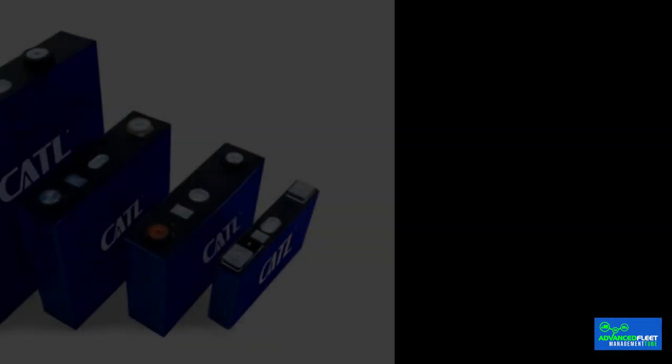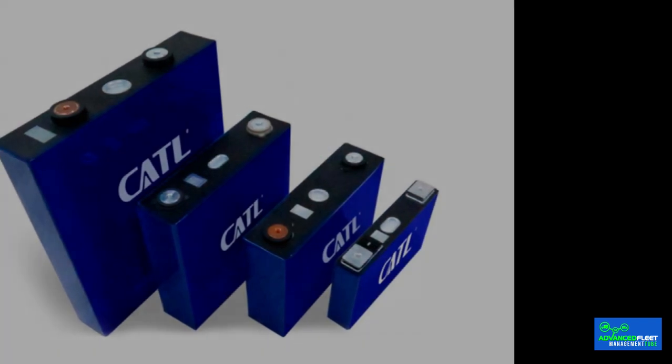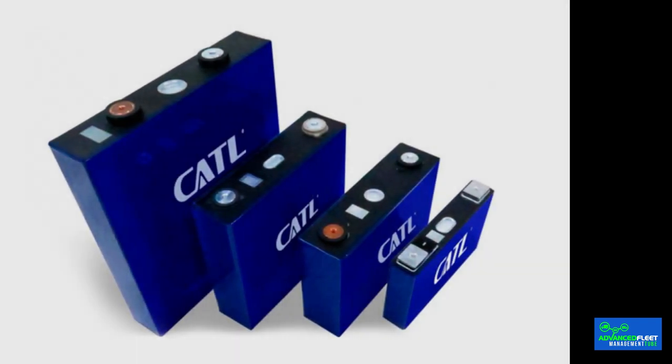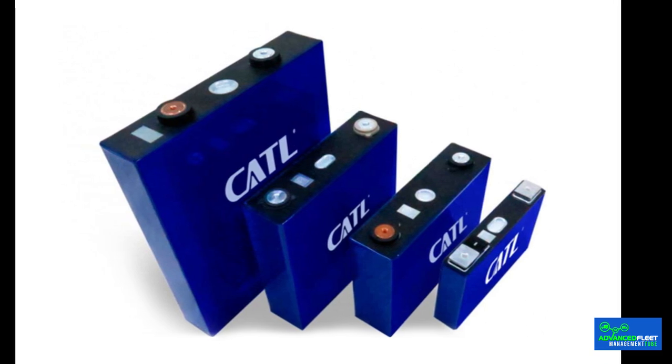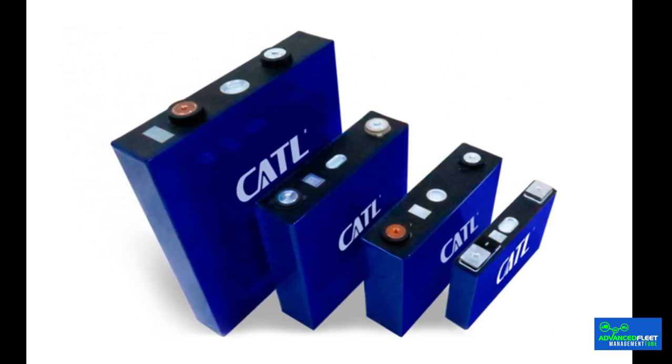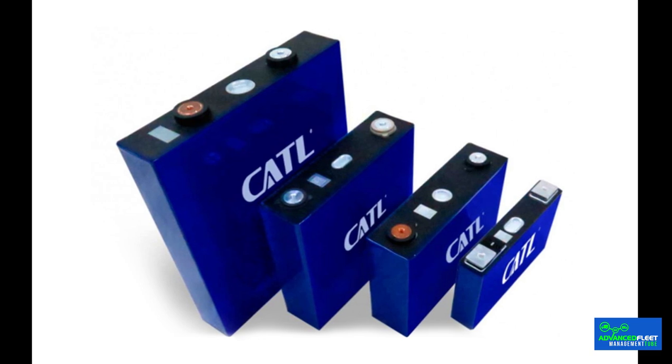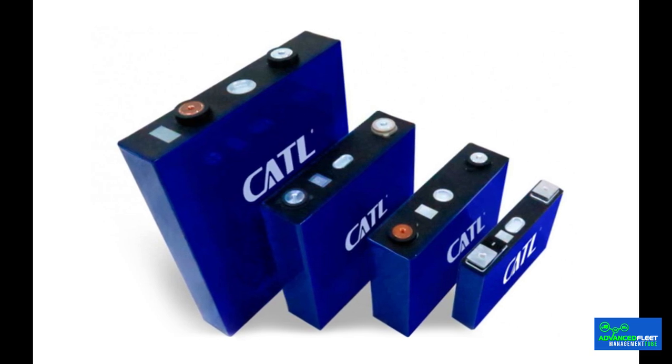Prismatic cells. They are characterized by their packaging capacity thanks to their stacked layer configuration. They are a battery geometry that is made up of a series of positive and negative electrodes sandwiched in a rectangular shape. The chemistry of a prismatic cell is enclosed in a rigid casing, mostly made of aluminum or steel, to ensure a high level of stability.